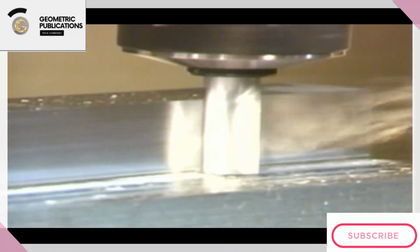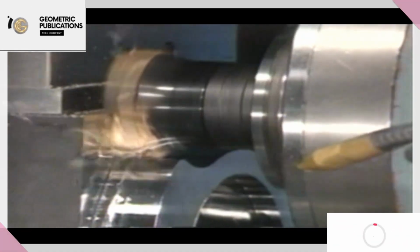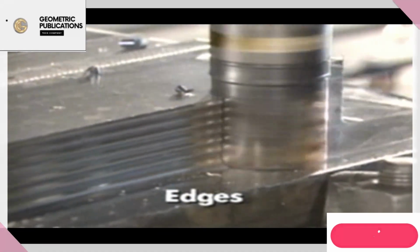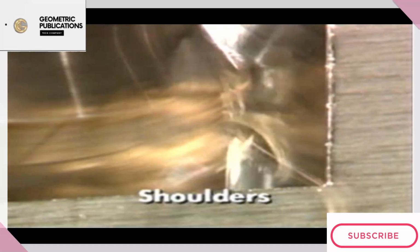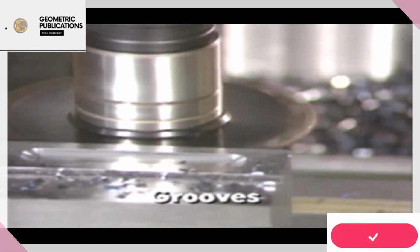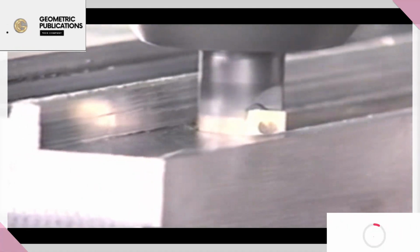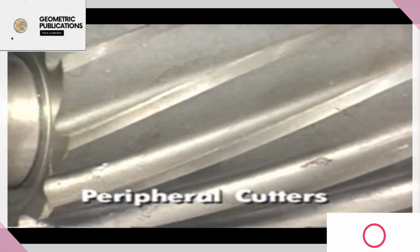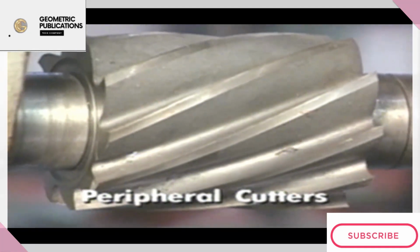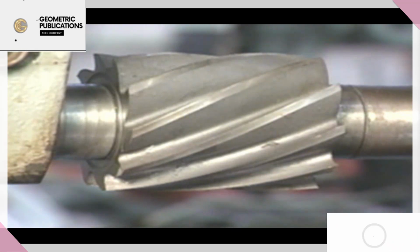Milling edges, shoulders, and grooves may use a combination of end, peripheral, and/or face milling operations. Edges may involve 1 or 2 surfaces, and the operation may be called edging. Shoulders typically have 2 surfaces. Grooves usually have 3 surfaces and may be closed at one end or open at both ends. Grooves may be cut on internal and external flat surfaces as well as round surfaces. Peripheral milling cutters have cutting edges on their periphery which are parallel with the axis of rotation. Peripheral milling is advantageous for long open slots and forms.